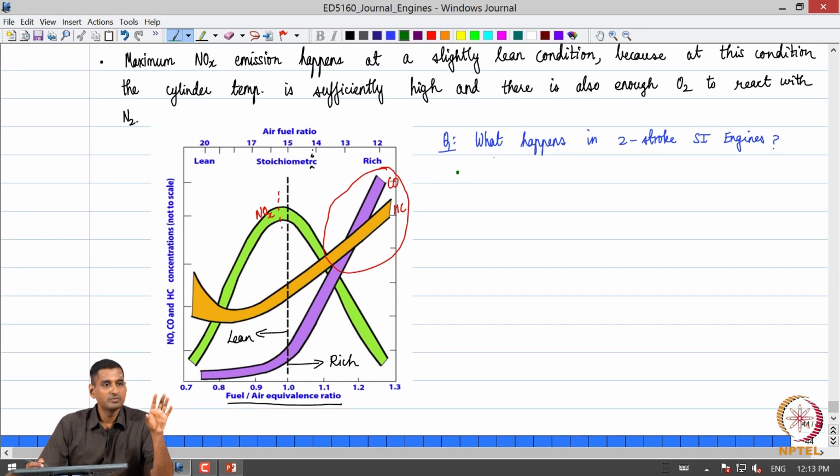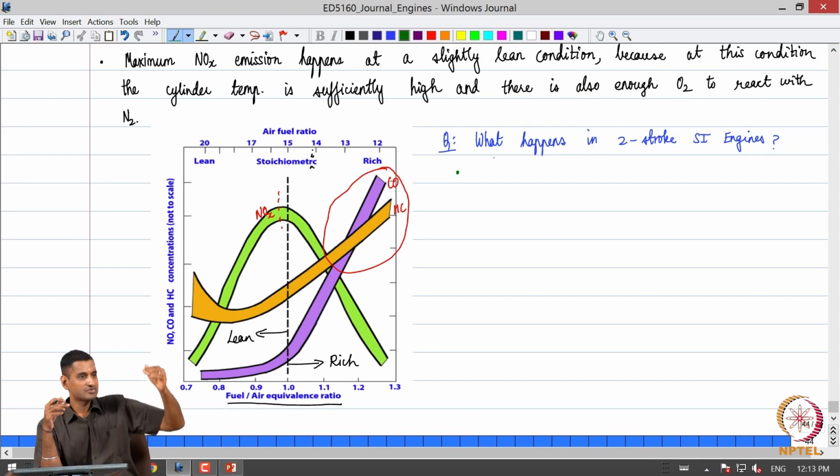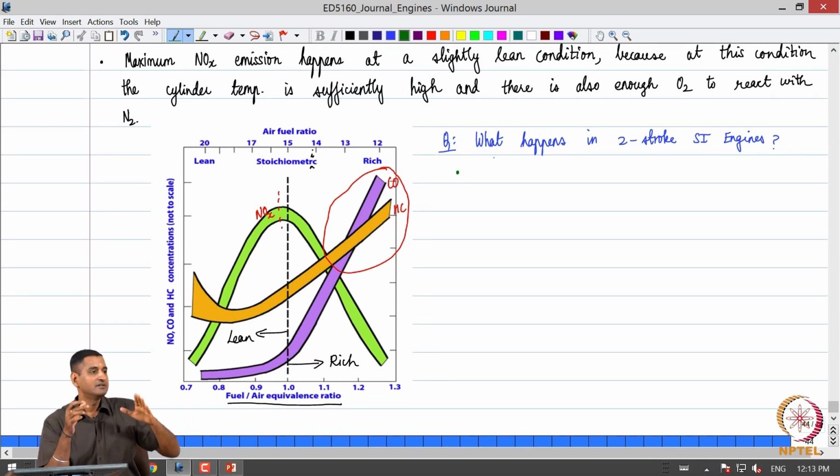If we recall how 2-stroke engines operate, the exhaust port is open during the downstroke, and during the same phase fresh fuel air mixture is going to come from the crankcase through the transfer port to the combustion chamber. So, there is a good chance of not only exhaust gas dilution of fresh charge but also fresh charge escaping into the exhaust port.